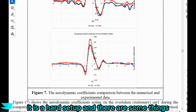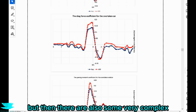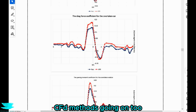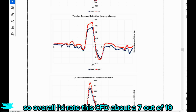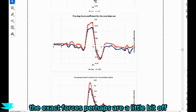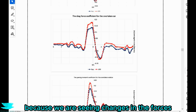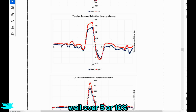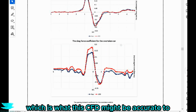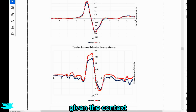It is a hard setup and there are some things that the researchers did to make it easier, like using armored bodies, but then there are also some very complex CFD methods going on too. So overall, I'll rate this CFD probably about a 7 out of 10, and we can trust the general trends and flow viz. The exact forces perhaps are a little bit off, but I don't think it matters too much here because we are seeing changes in the forces well over 5 or 10%, which is what this CFD might be accurate to. So I think the force coefficients can largely be trusted here given the context.